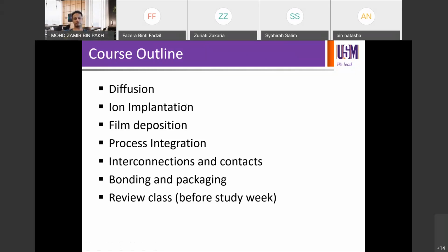We've learned about film deposition by PVD, by E-beam evaporation, by thermal evaporation, by sputtering, DC and RF. And you've also learned various methods of CVD, chemical vapor deposition, in order to deposit different layers with different properties. And then we learned about process integration from day one of the processing until you get to the surface preservation layer and the bond pad.